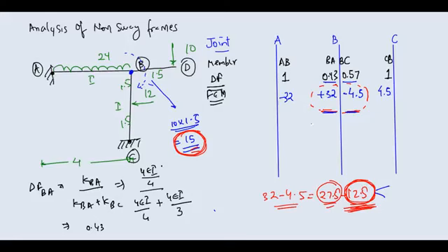I think here you will get minus 5.37. How are you getting this 5.37? 12.5 into 0.43. 12.5 is what I have to subtract from here, and 0.43 is the distribution factor, and on the right side you will have 12.5 into 0.57, so here you will have minus 7.12. Now if you sum them up, from this red circle you will get a net value of plus 15. Is it okay? You can calculate on your own. You will get a value of plus 15 from this red circle.